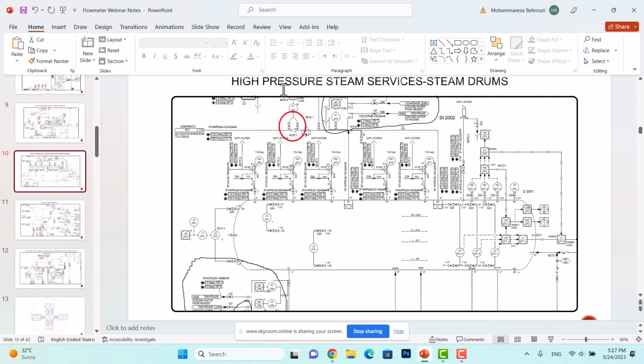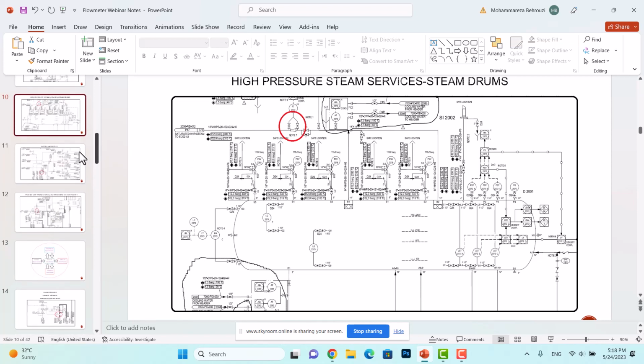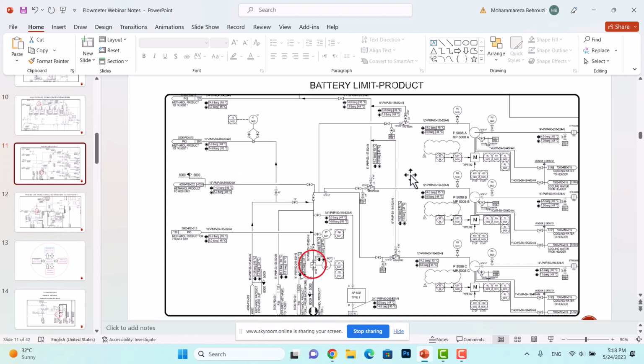And for such applications, we are supposed to use the flow nozzle flow meter type. And Coriolis flow meters. As I stated, based on that table, when we are dealing with product flow rate measurements, we are supposed to use Coriolis flow meters. Coriolis flow meters are the most expensive compared to other flow meters, and they possess the highest accuracy.